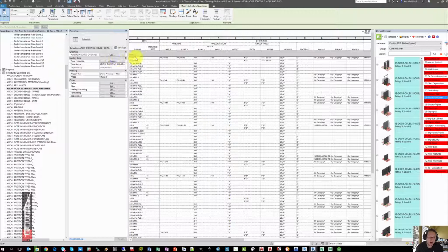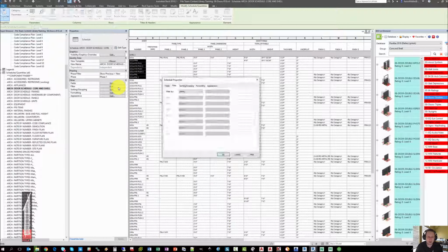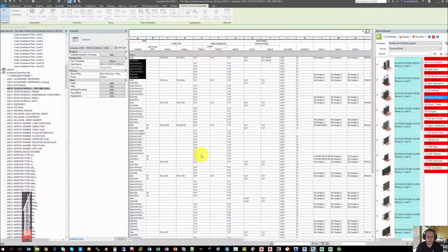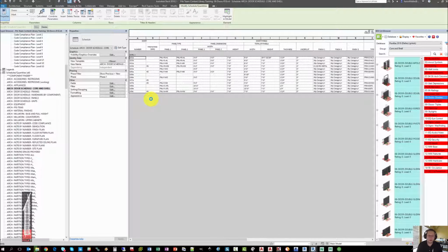For instance, all of those lines are really just door 101A. Don't worry, now that you know what the filter is, which again is also in your door PDF guide, if you simply go back in and say panel 1 exists and unit door does not equal yes, then you'll find that your door schedule completely goes back to normal instantaneously.